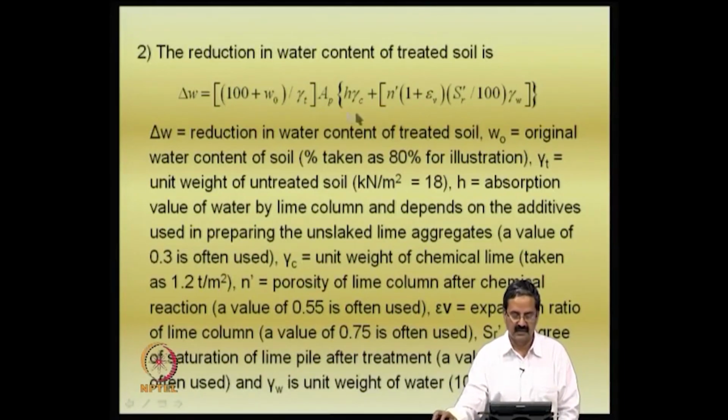This expression is based on heat of hydration and other things, and it is given in the literature. The reduction in water content of the treated soil depends on the initial water content, which I am taking as 80%. This water content is very high; it may exist in Vizag soil or some place on the east or west coast. The unit weight of the soil I have taken as 18, and H is the absorption value of water by the lime column, which depends on the additives used in preparing the unslaked lime aggregates.